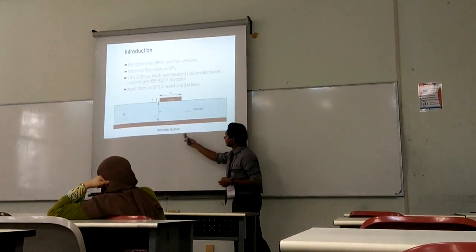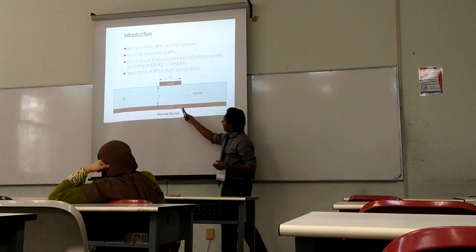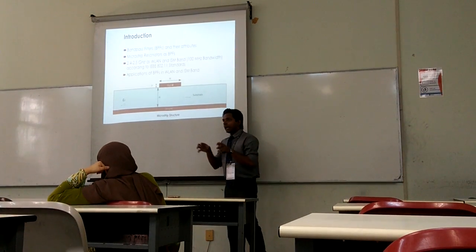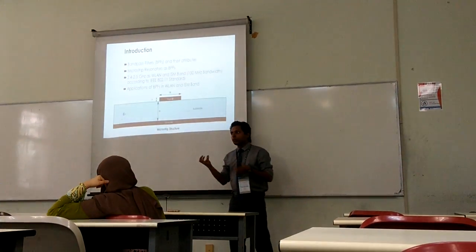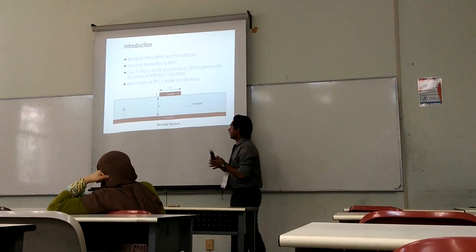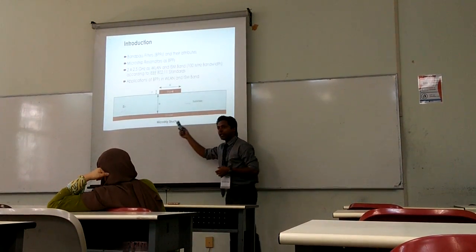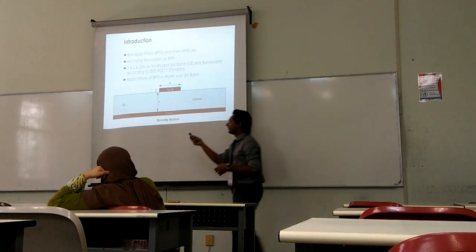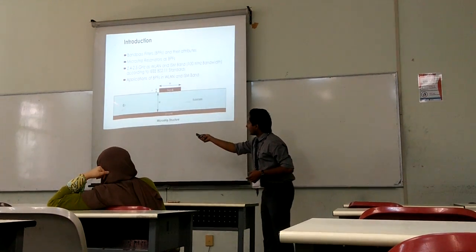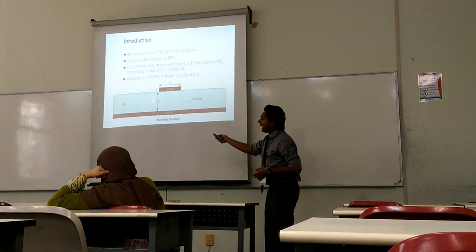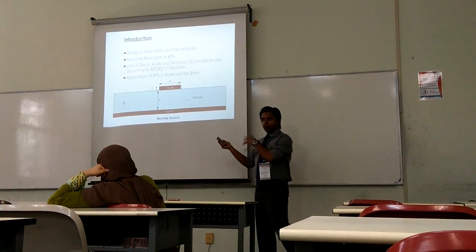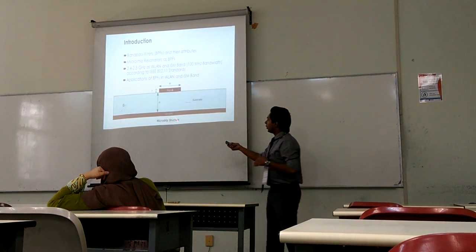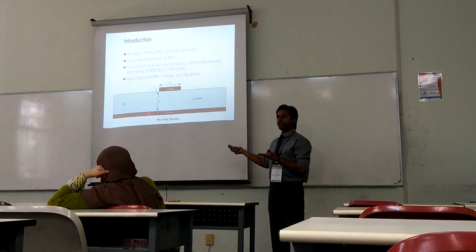Let's look at the picture first to demonstrate what is the base of the microstrip. You see there are three layers. The top layer, we call it the signal layer. We propagate signal through this layer. And we design, for example, for antenna we design a patch. For filter we design a resonator at the top plane, that is the signal plane. After that we have the substrate as dielectric material with a specific dielectric permittivity. This is the dielectric permittivity, and this is the height of the substrate. This all determines something we will relate later on. And there is a ground plane. This is for grounding the signal. We can also work on here, for example, the defected ground structure.